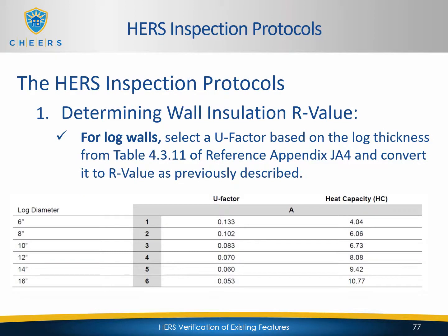For log walls, select a U factor based on the log thickness from table 4.3.11 of reference appendix JA4 and convert it to R value as previously described. And this is the table that I just mentioned.